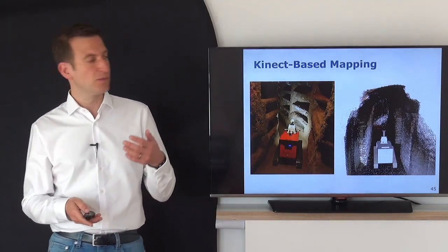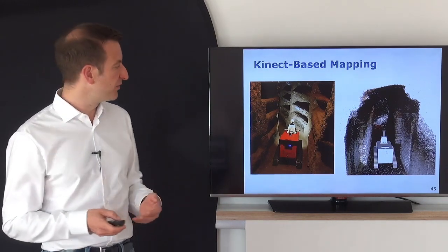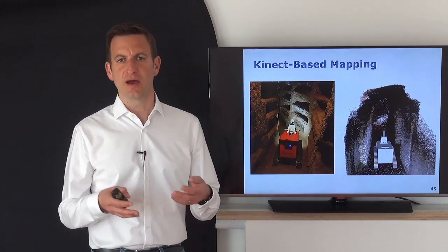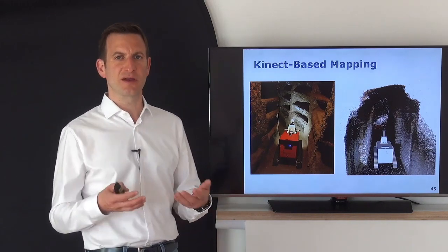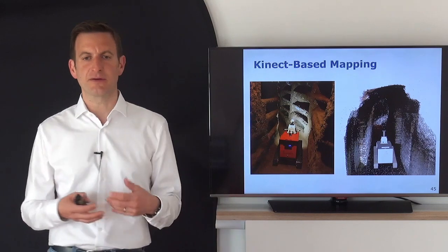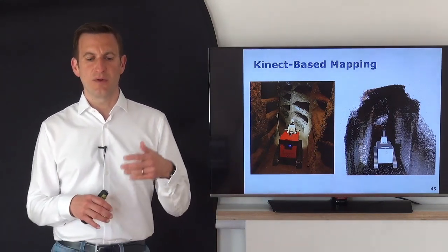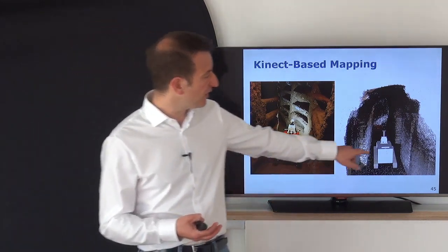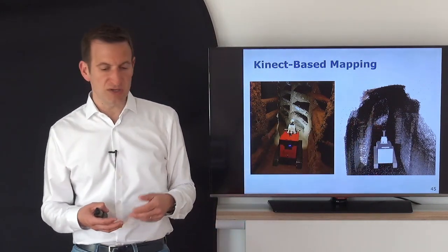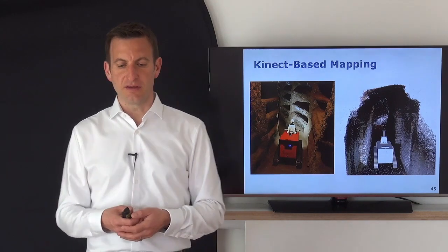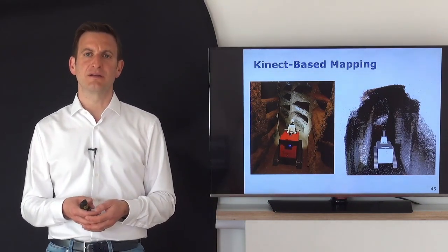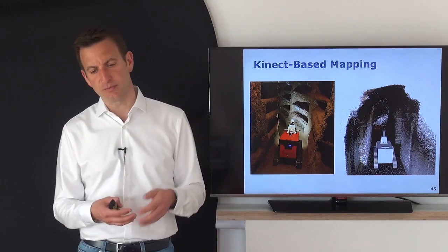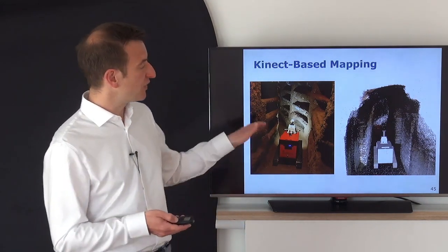Just a few examples here. What you see here in that system is a robot that we have built to explore Roman catacombs within a European project. And it also used a mapping system taking into account the data from a Kinect-style sensor, actually from 3 different Kinect-style sensors installed on the front of the platform, perceiving the environment and registering them with the help of the ICP algorithm into a consistent set of point clouds, and then running a SLAM algorithm. So here on the side you can see, for example, part of a scan which has been taken from multiple of those Kinect scans. The approach used here was so-called NICP, a variant of the ICP algorithm developed by Giorgio Grisetti and his team from Rome, that specially takes into account normal information to improve the registration, make the registration more efficient, just as one of those examples.